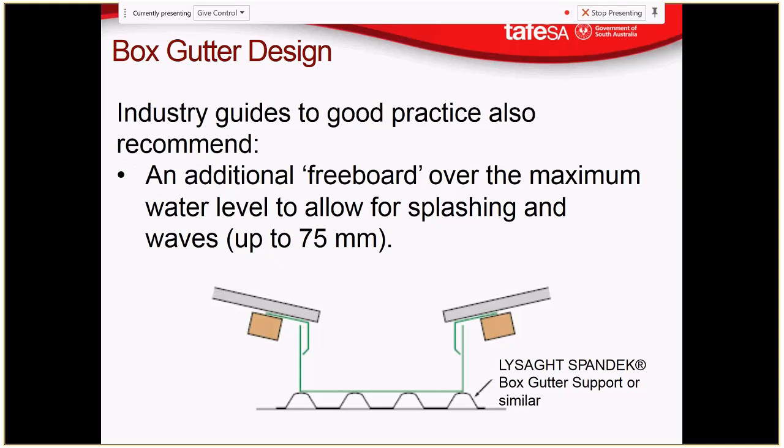However, when we go designing box gutters, typically we don't go, okay, this is the amount of cross-sectional area which is going to be filled with water. We allow the Australian standard to have specified all of that, and then we just go through the calculator, either in the Australian standard or an online calculator, to do that. And it tells us the height of the box gutter.